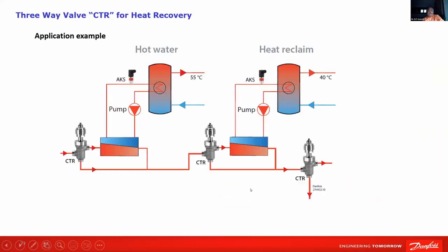Heat recovery. In this diagram, this is the compressor inlet and compressor outlet. And before the gas cooler, you introduce two heat exchangers for hot water recovery, heat recovery. In this example, there are two hot waters shown. This one is used as tap water. Tap means in cold climates you need hot water for bathing or even washing the hands at 55 degrees. The other one, in Europe they generally use for floor heating or even outside the supermarket where the road is frozen. You circulate the hot water to keep it, if not warm, at least melt the ice. That's why two are there.